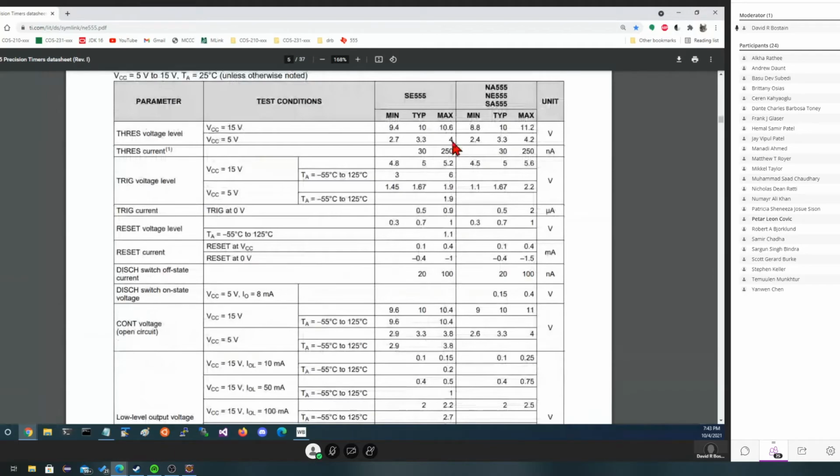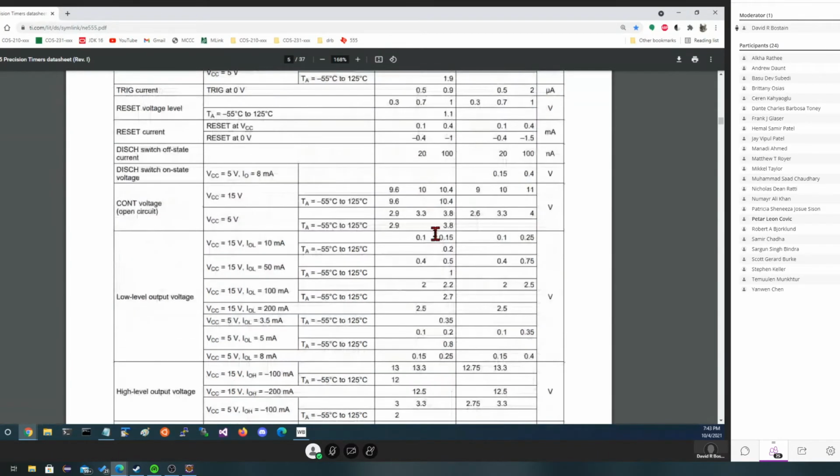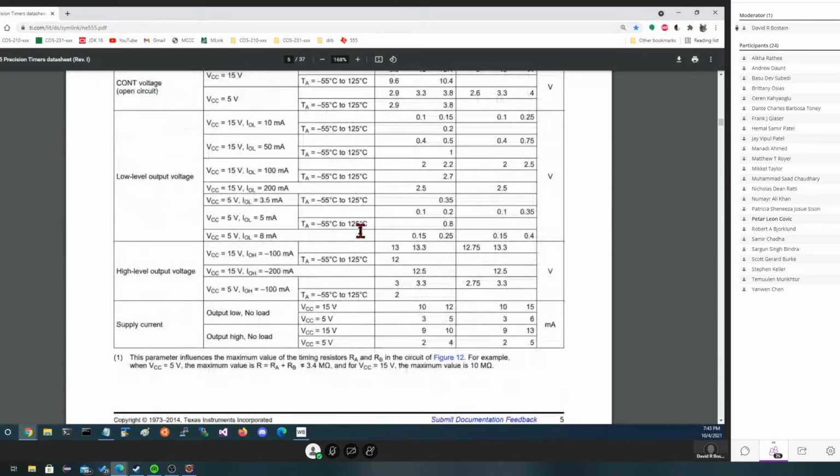And finally, the characteristics of the pins. They are specific per pin, and we would check this data sheet. But we did learn that they are compatible with TTL. So if we just wire it up, we'll get voltages, as long as we stay near 5 volts for VCC, which meet the requirements here. This is worth running your eyeballs over because there could be a test question about it. But you know how to find this page, and then it's just look it up.